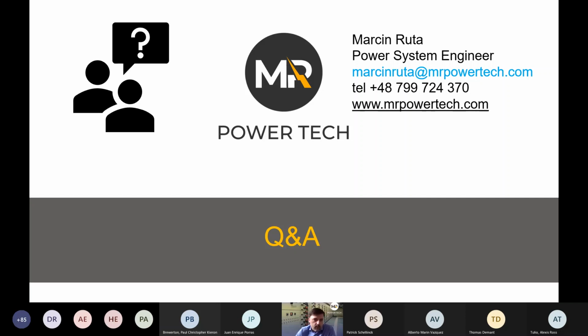But if it comes from protection, you might check if you can improve it. Very often you can improve it, so dropping below 40 calories is very easy. If you cannot drop below 40 calories because you have some medium voltage fuse or something different, then you might look into mitigation techniques such as an arc flash detection relay or arc flash relay. That's also very easy to do.